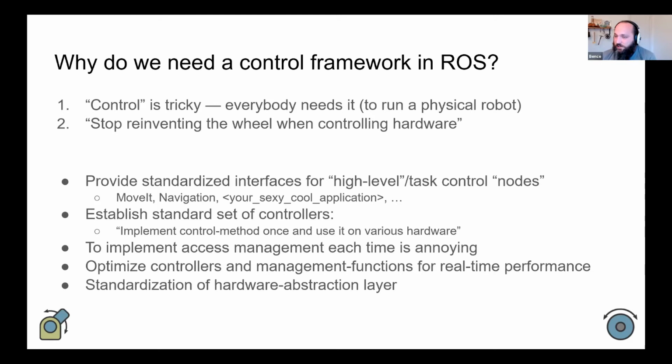It solves the control of a differential drive mobile platform that was then extended to handle skid steering and also to handle multiple wheels, still differential drive, and then expanded into a 4-wheel drive thing, and then an Ackerman thing as well, still springing from the same code base. And this particular controller was actually worked on by multiple companies at the same time, all using it in their products. So I was very happy to see that happen.